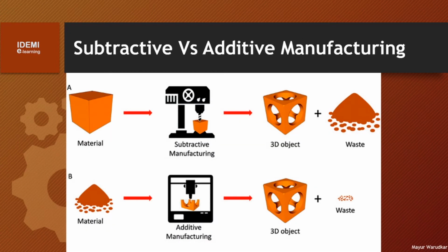Both additive and subtractive manufacturing have revolutionized the way products, parts and prototypes are made. Additive and subtractive manufacturing technologies are advancing rapidly. Rather than adding layers, subtractive manufacturing involves removing sections of a material by machining or cutting it away. It can be carried out manually or, more commonly, by a process known as computer numerical control, CNC, machining. Additive manufacturing is a process that adds successive layers of material to create an object, often referred to as 3D printing. The waste generated is less compared to subtractive manufacturing.